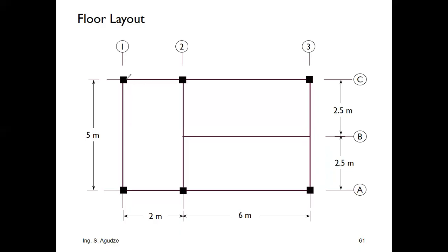Okay, so you see that these big black ones are the columns, okay? And all the black lines are the beams, right? So if you can see clearly, this beam here is a secondary beam. So if it's a secondary beam, if we are sketching this beam, you see that this one will be like this with a support like this, and then this beam will cut it, half comes here, half goes here, and it's going to be like this with a point load, right? Good.